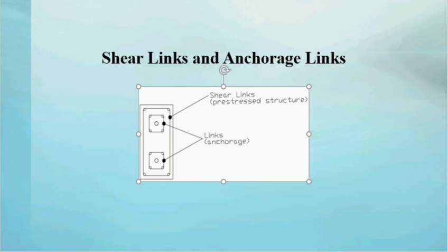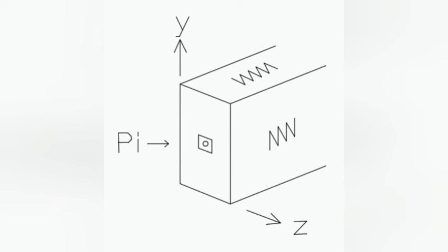Okay, the summary for this study is the possibility of cracks in the anchorage zone after force is applied from the post tension cable. After doing the simulation on two cases, we can predict what and where cracks might happen after a certain period, depending on the arrangement of the post tension cables. For this study, a single concentrated point load tends to have a crack along the middle of the height of the beam, while two symmetrical point loads tend to have a crack along the middle of the beam width.